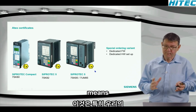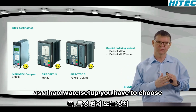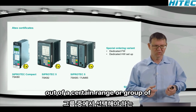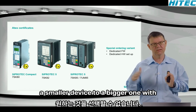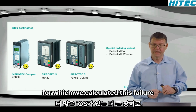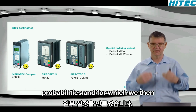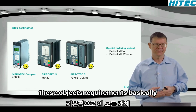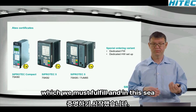That means you cannot just select whatever you like as a hardware setup. You have to choose out of a certain range or group of devices. So we made some setups from just a smaller device to a bigger one with more IOs, for which we calculated these failure probabilities and for which we then started to prove that we fulfill all these ATEX requirements. Basically, what is behind this SIL level 1, which we must fulfill.